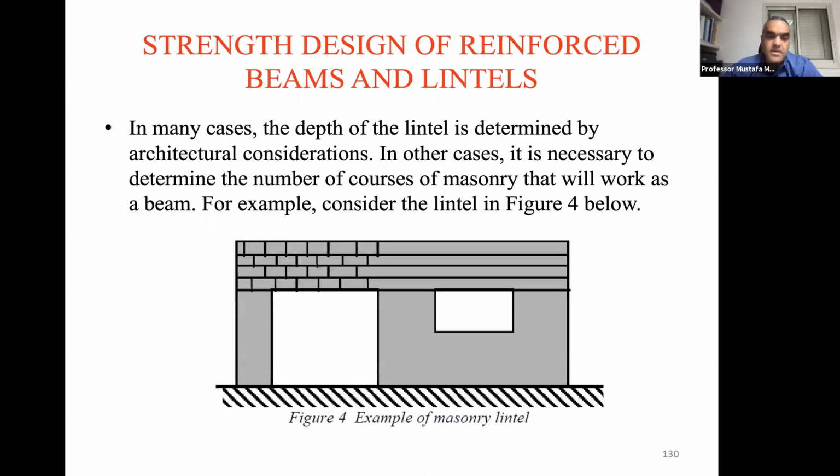So this is an example of lintels, like over an opening. You can see here we have 4 blocks, right? If each one is 8 inches with the mortar joint, that's 32 inches. That's a very deep member. So look, even to scale, at the depth compared to the opening itself. So this could be enough. And that's why we will end up maybe with really the minimum reinforcement in the lintel, maybe one rebar, which is the minimum, by the way, 1 rebar or 2 rebars.